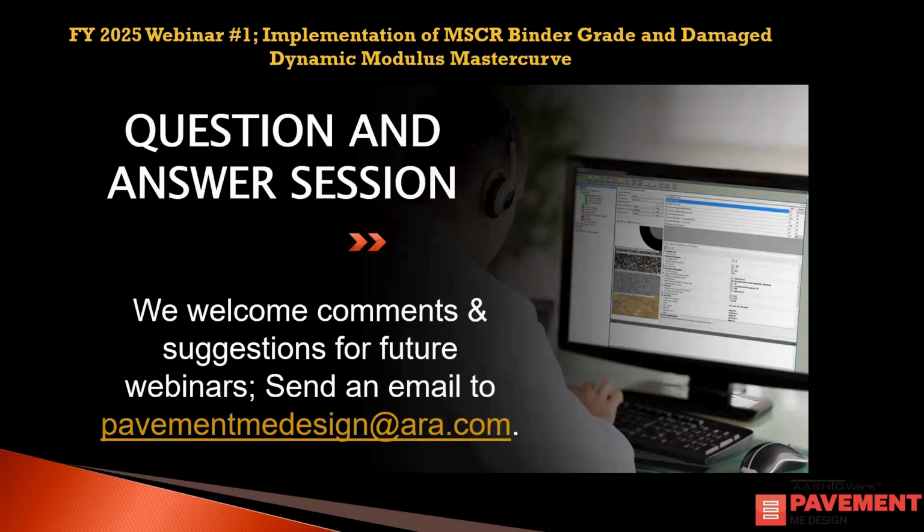Yeah. Wouter, the next question is, fatigue curve improves for lower moduli. This is true for new hot mix asphalt, but may not be for old hot mix asphalt. Are there plans to adjust the fatigue law according to damage? Not sure, Wouter, but yeah, I'll plan to adjust the HMAC fatigue law.